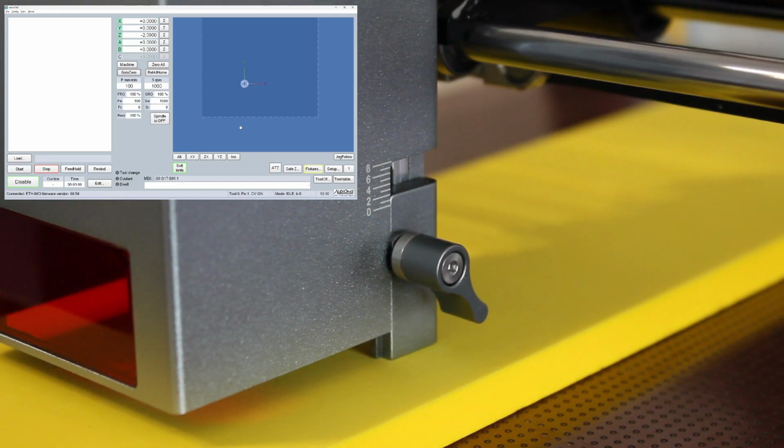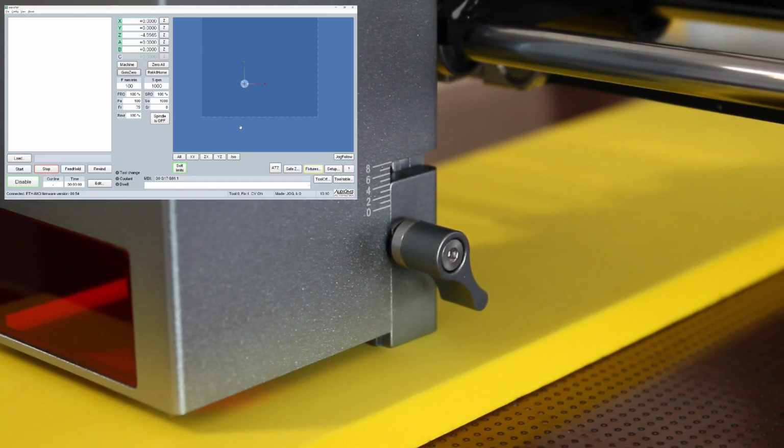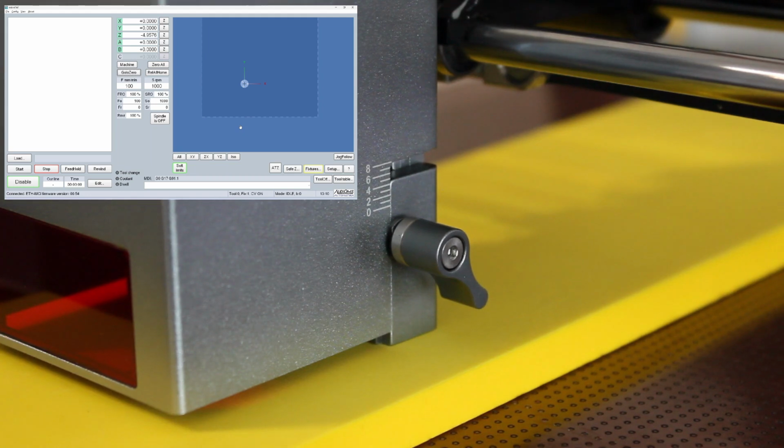material. If we wanted to engrave something onto the material, we would set the focus at the surface. But since we want to cut the piece of foam, the focus should be set at the half of the thickness of the material. So we will gently move the Z-axis until the ruler indicates 5 millimeters.